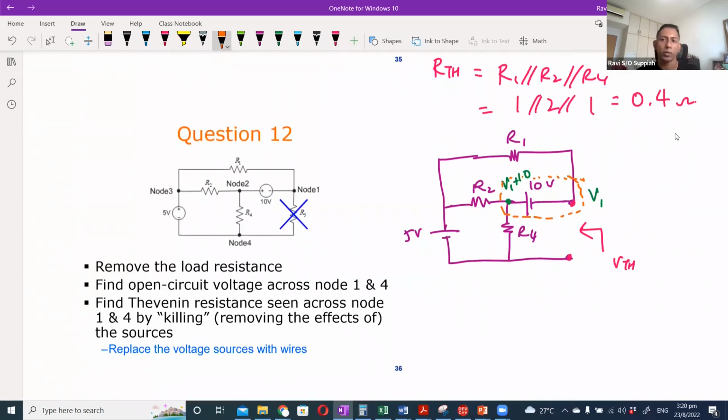Okay, so again, this node voltage analysis is quite useful, correct? When you see the circuit is a bit complicated, you're not very sure how to do it, then by declaring nodes, especially with the power supply in the middle, you declare one end as V, the other end as V plus the supply amount. That itself can help you to have a single expression to solve for the unknown voltage. Okay, so with this, I can come up with my expression.